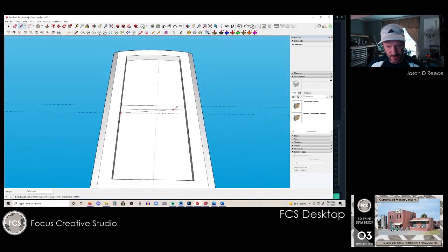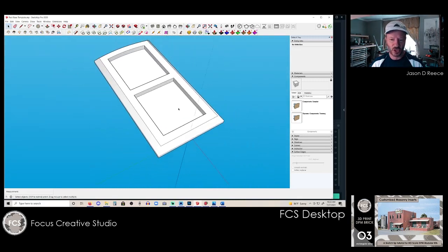This bridge here in the middle gives me a place to anchor some supports right there in the middle of the model that just provides some stability as you're printing. The goal is to prevent the warping, and so that's just what we're looking at here, is how do we create some anchor points and develop a system that keeps this piece perfectly flat while it's printing and curing.